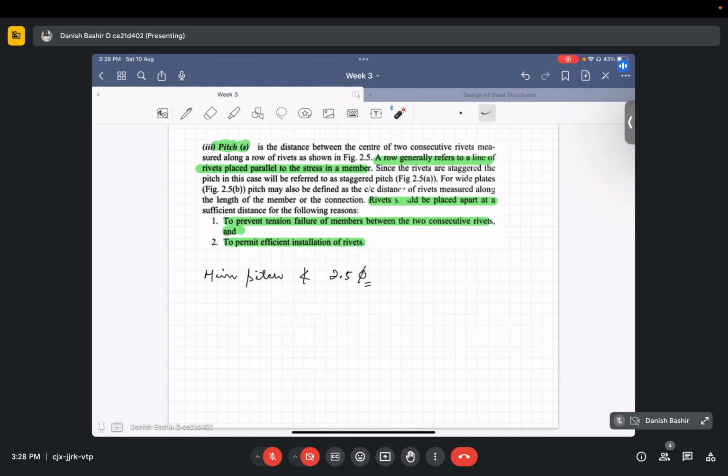There is one more limitation, the maximum pitch. There should be a restriction on the maximum pitch. So the distance between the centers of two consecutive rivets in the direction of the stress should not be greater than 16 times the thickness of the plate or 200 mm, whichever is less.